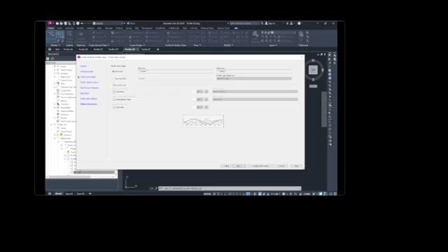Profile view height page. We're gonna set up some parameters. Profile view height, user specify, is 50. Profile view datum by mean elevation. Split profile view selected. Click next.